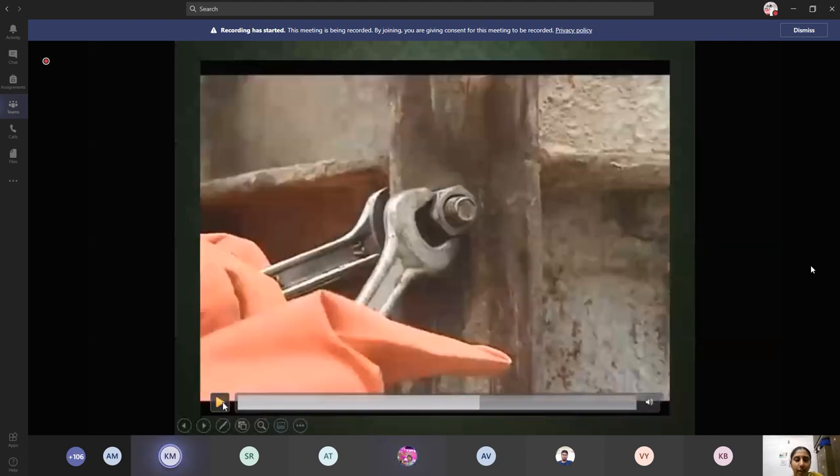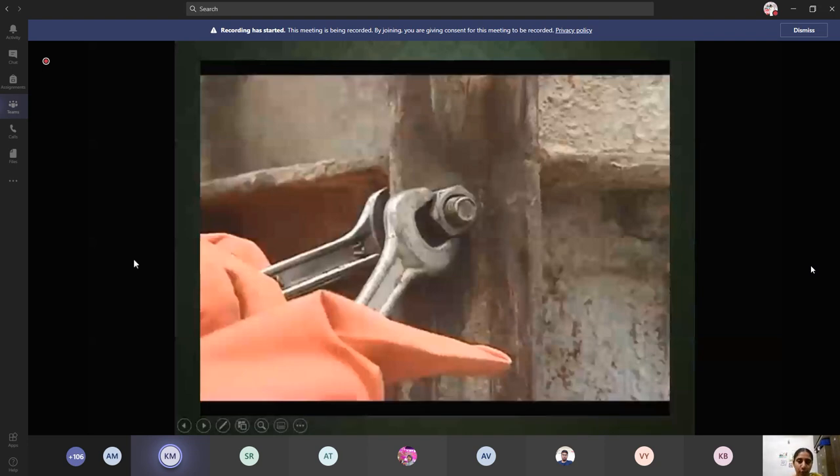Okay, no problem. As of now, we have seen that there is going to be a vertical sole plate. It will be like a clam shape, that is L shaped at the sides of the footing. Over that, in between, you have your reinforcement cage. They're going to fix this L shaped box over that sole plate. They're going to fix it because they should ensure there is firmness between the sole plate and the vertical member. Now they are just fixing it with the steel.